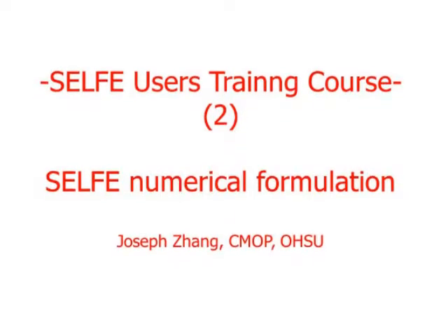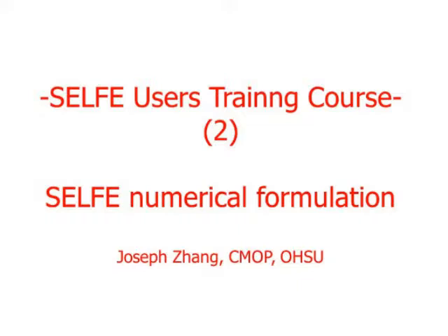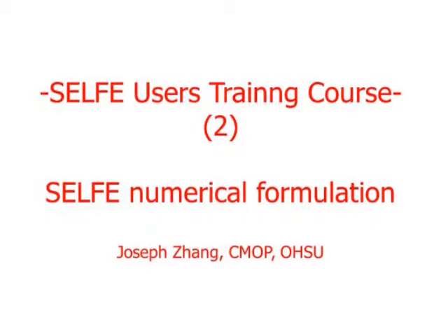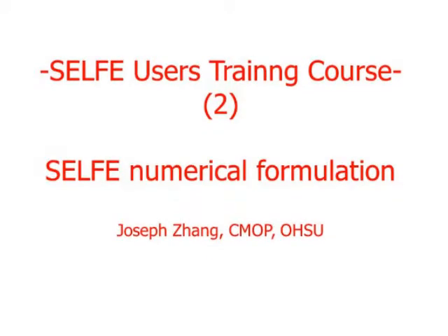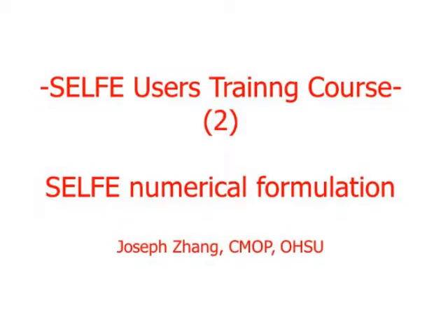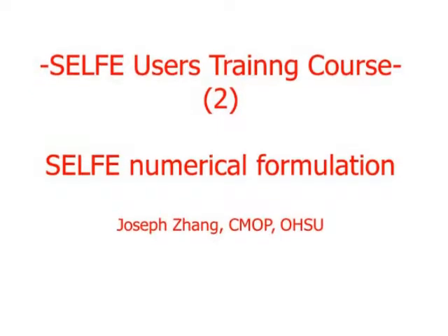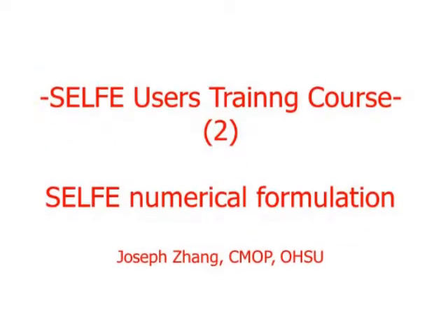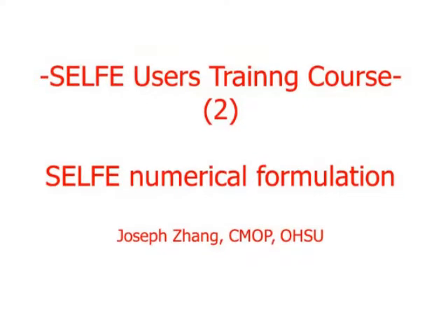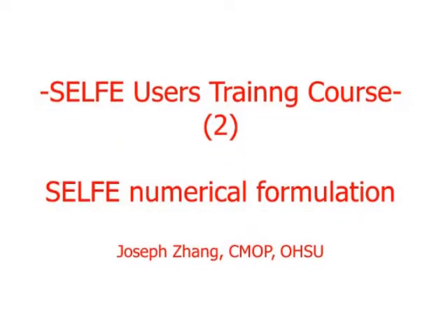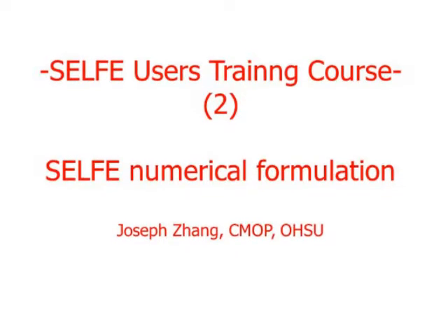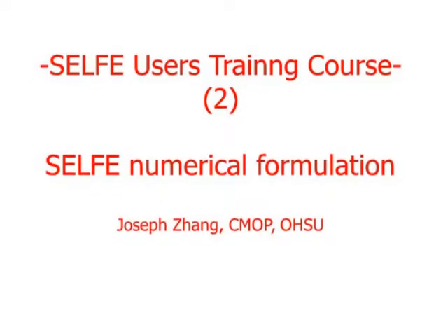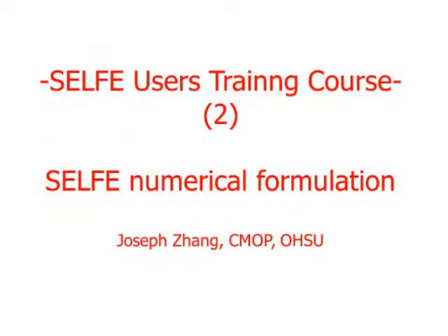So in a 2D sense, if you look at this region around a particular node j, the shape function associated with this node j is 0 everywhere except 1 at this point. If you can imagine in 2D, it's basically shaped like a pyramid. And outside this immediate region of concern, the ball of the node, the shape function is 0 everywhere. So it's a global concept. Don't get confused, because most times we are using the shape function in a local sense, but it's actually a global quantity.